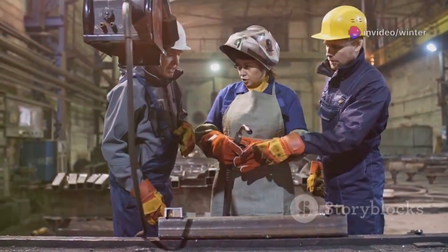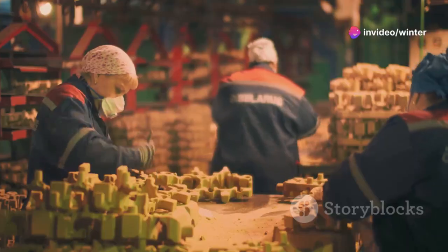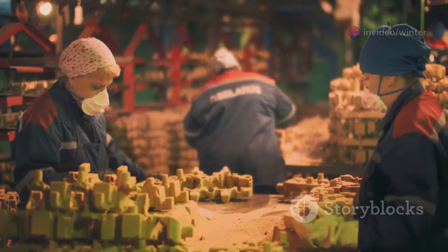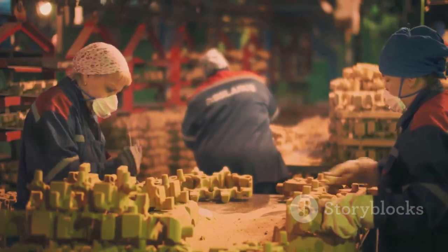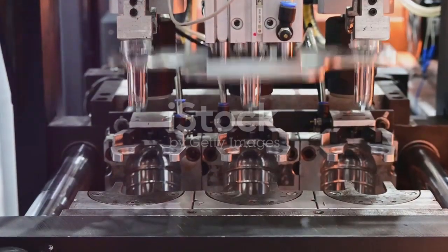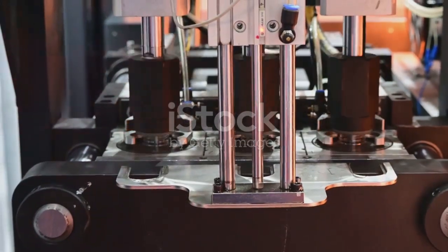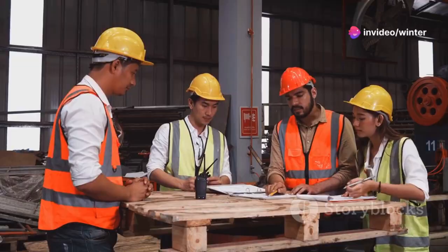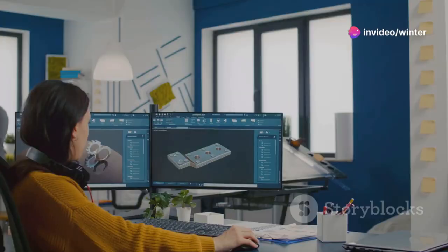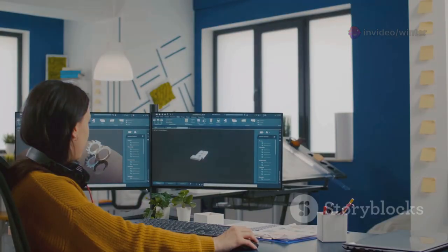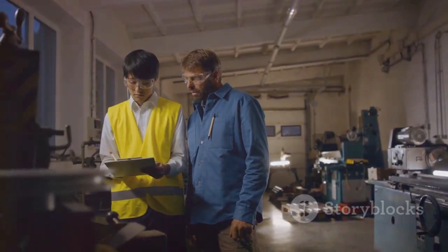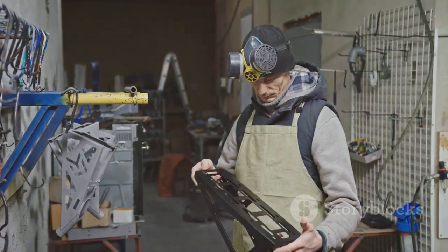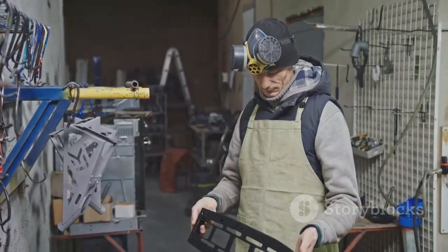There you have it, 8 strategies to slash injection mold costs. Simplify geometry, add draft, minimize side actions, standardize. Choose the right runner and material, apply tolerances wisely, and design for maintenance. It's about holistic, practical engineering from day one. Optimize in CAD to save thousands in tooling. Use these principles as your checklist for every project. Challenge every feature and plan for the tool's full life.